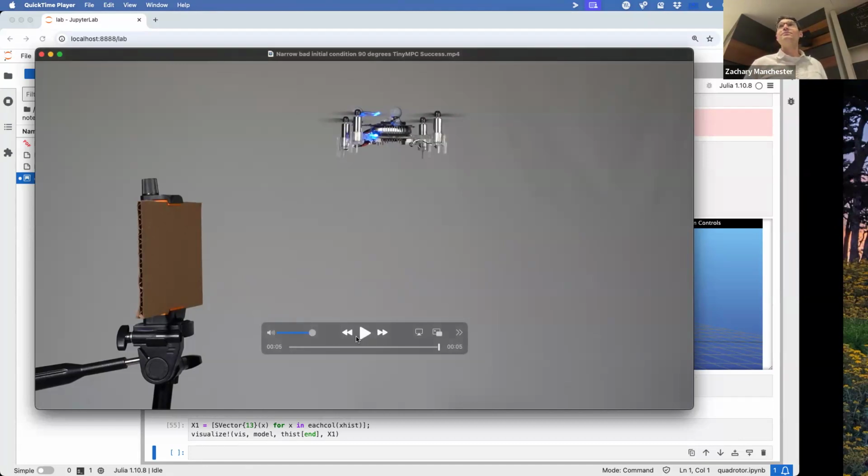Did you take measurements to get all the experimental data we were talking about, like your moment of inertia? Yeah, so I think actually we fudged a lot of that. Obviously mass you can get on a scale super easily. I think we grabbed their stated inertia numbers from the Crazyflie code or papers. We didn't actually measure it. We just grabbed the rough numbers from their CAD, I think, ultimately. And all the prop coefficients we grabbed from their code. We didn't do our own SysID or characterization really. We just used the numbers that were floating around in their firmware or published elsewhere.